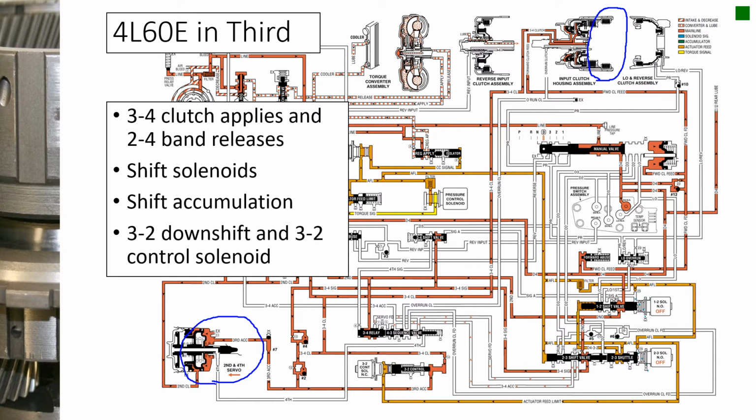There are some transmissions that are out there, and really no new ones anymore because there's just too many speeds to make this happen, that don't have any synchronized shifts, like a 4L80 for example. When you shift from first to second, they apply an intermediate clutch and then the low roller freewheels.